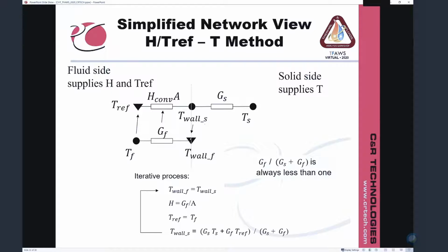So we tried the convective coefficient reference temperature method, which is the most common method of doing this kind of coupled problem. In here, instead of getting the flux that the fluid program computes, the fluid program will convert that into some free stream temperature or Y plus temperature. There's a variety of schemes for figuring out what a good fluid temperature would be, and a convection coefficient. That physically makes sense. It's nice, but you can see how this anchors the wall temperature.